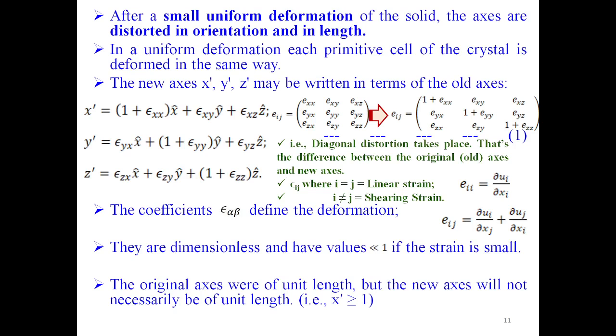So in this case, the displacement u along x direction divided by the unit change in length along y direction plus the displacement of u along y direction divided by unit change in length along x direction. So this is for the strain with the mixed indices.